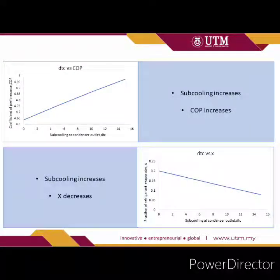Next, we go to the third graph of this case study. The graph shows us the subcooling versus coefficient of performance. As we increase the subcooling, the COP also increases. Next, we go to the last graph of this case study, which shows the subcooling versus fraction of refrigerant evaporate. As we increase the subcooling from 0 to 15 degrees Celsius, the fraction of refrigerant evaporated decreases.